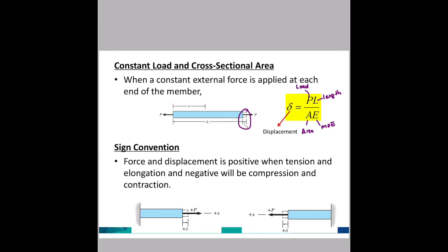Remember the sign convention that you had in chapter 1 for the internal resultant forces. If you take the section from the left-hand side, all the internal forces should be positive to the right. If you take it from the right, then the internal forces should be positive to the left. This is a sign convention you need to remember until year 4 in structural subjects. So please remember the sign convention, whether you take from the left or from the right.